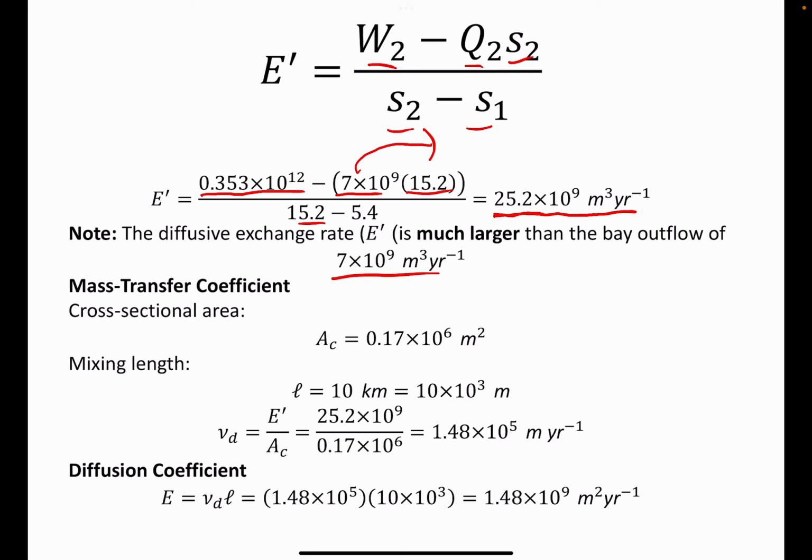The E prime, which represents the effective volume of water that is being mixed back and forth between the bay and the lake. Of course, the mixing back and forth between the bay and the lake, because of turbulent diffusion and circulation. All of this is happening, and that is much more important than the actual water flow.